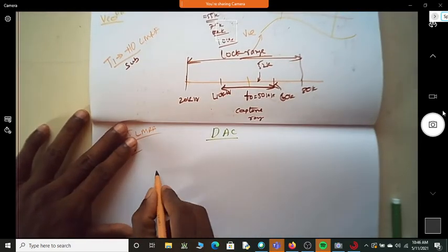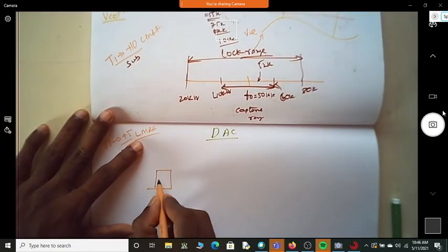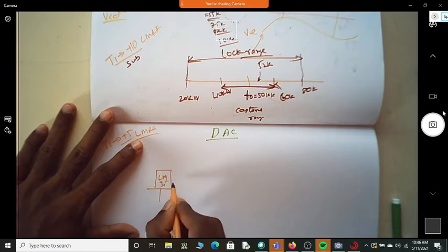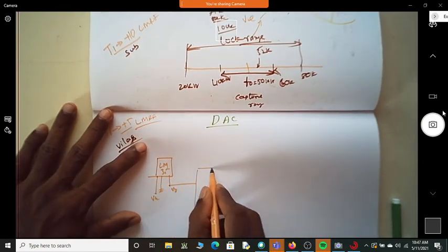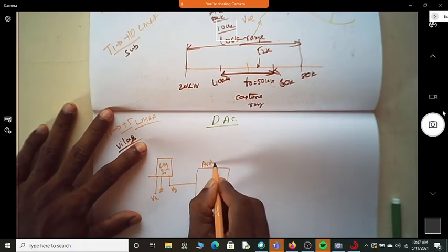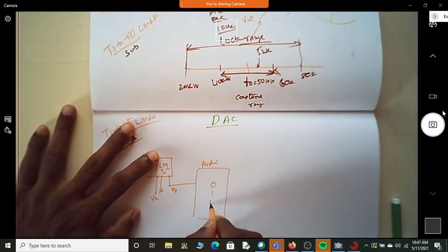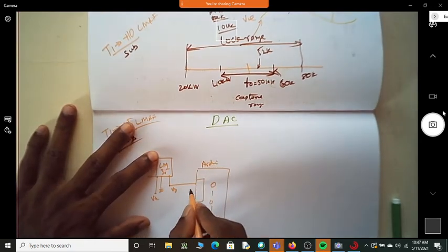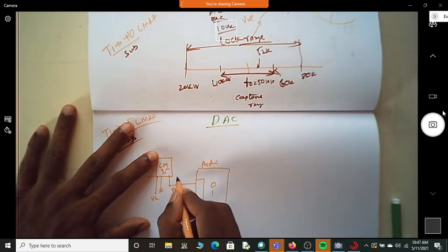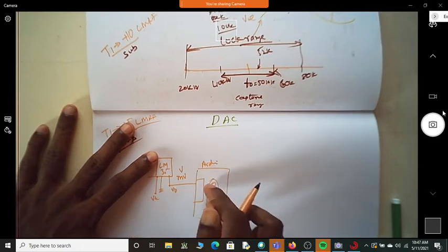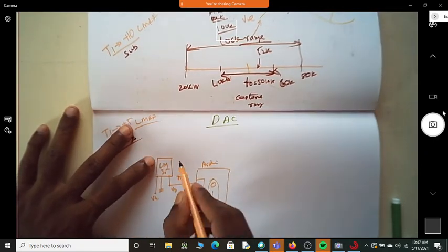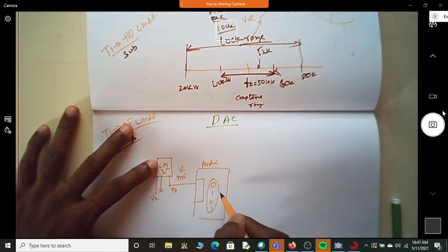Nine. What I have is, so this is what you had, no? This is LM35. So you had a ground, of course, you have a VCC, and then you have a V0 here. This was actually connected to what? Arduino. This will handle zeros and ones, correct? What was there here? This is analog signal. This is in terms of millivolt, or it can be in terms of volts. But this knows only zeros and ones. How do you convert this millivolt and volt to zeros and ones?